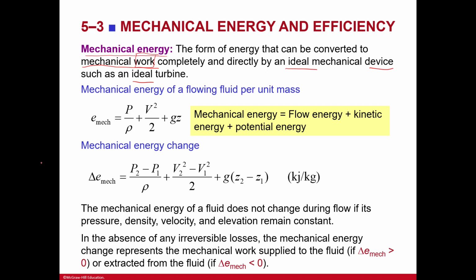So here is the mechanical energy. Mechanical energy is equal to flow energy plus kinetic energy plus potential energy. And this is the energy change, the change of mechanical energy. Here, the mechanical energy of a fluid does not change during flow if its pressure, density, velocity, and elevation remain constant, right?